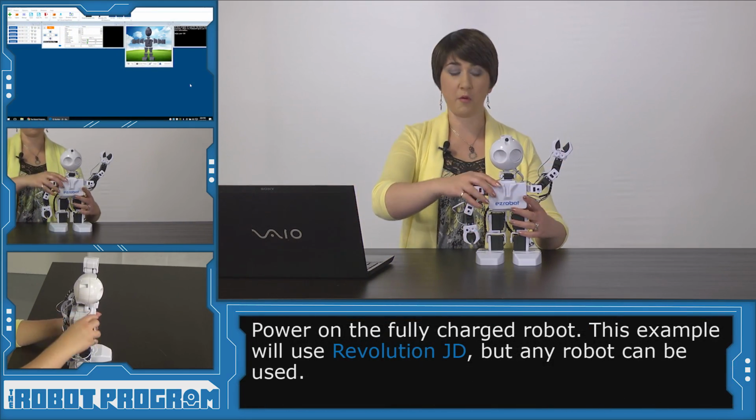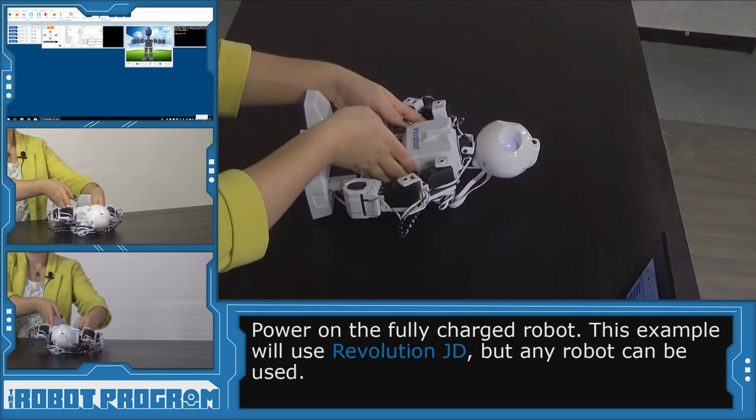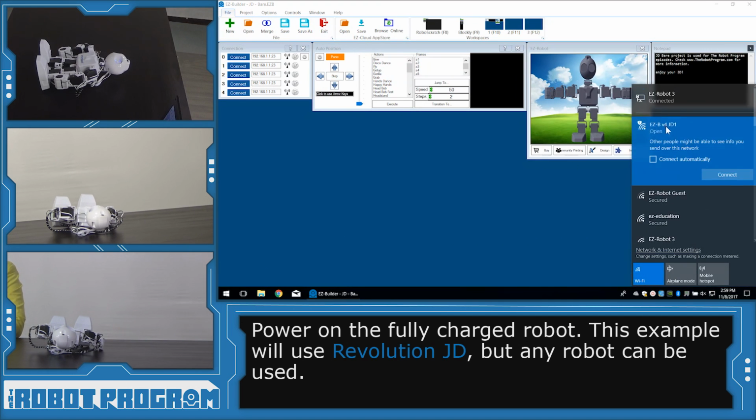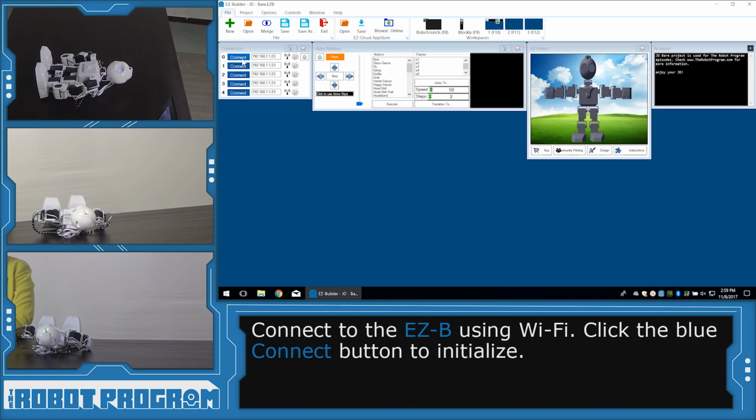So I want to power on my robot, and we're going to lay it face up. Then under my connections, I'm going to choose my EasyBee V4 connection, click Connect, and then click the blue Connect button and give JD lots of room to go into the initialization position.